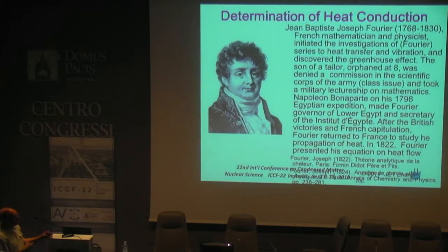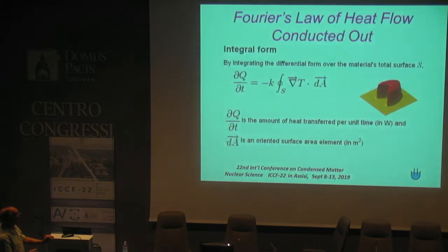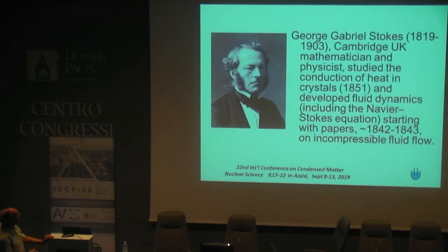And we know that with heat conduction, we put a surface integral on. We can look at the amount of heat that goes through. We do that in all our calculations when we calculate T1 minus T2, the outside ambient versus the core, and that gives us the heat flow. So here, for example, the heat loss that occurs through a volume goes as the surface integral and the gradient of the temperature, and it's actually quite easy to do.